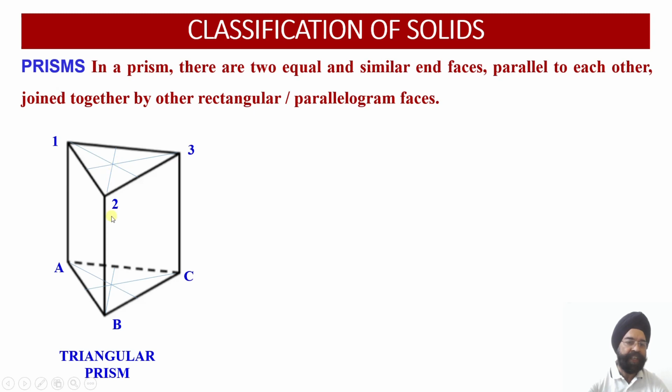Wherever these bisectors meet, either in the front or in the top, this gives me the axis point. The axis point I can name as O over here, and this will be named as O1.